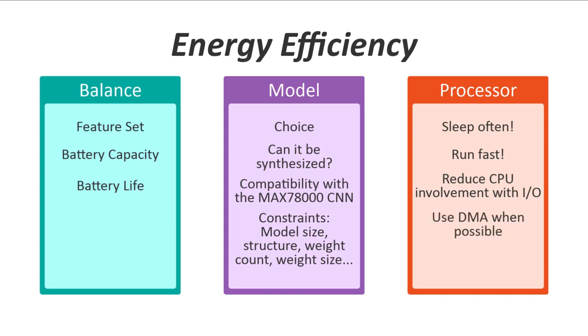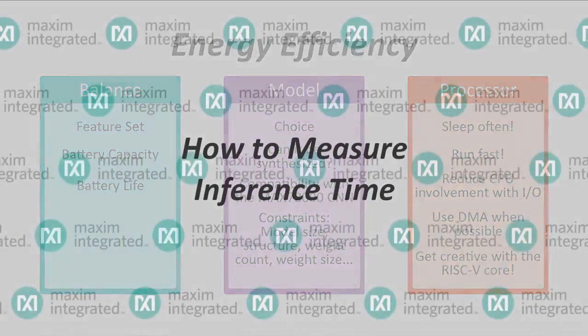The RISC-V core can also be leveraged to serve as a smart DMA engine, but in our experience the RISC-V does not contribute much in the way of energy savings unless its operation can be pipelined with Cortex and CNN activity. Generally speaking, if you need to burn CPU clocks, the Cortex is the best option due to its substantially higher clock frequency. This is just a rule of thumb though, and you may find innovative uses of the RISC-V core in your application.